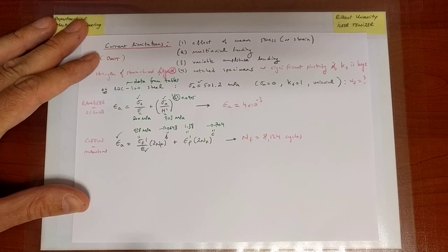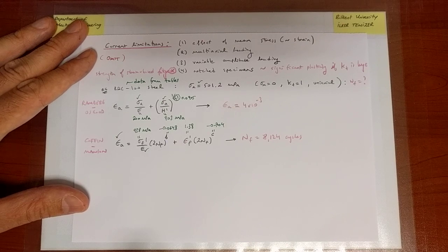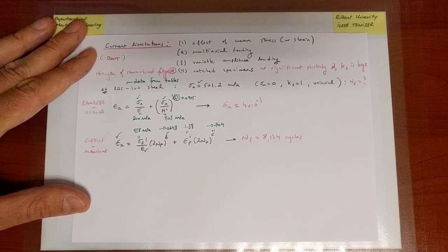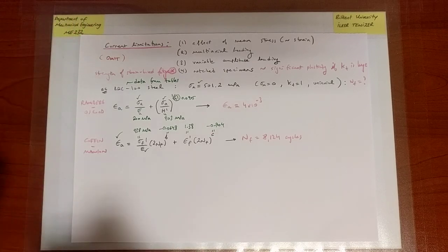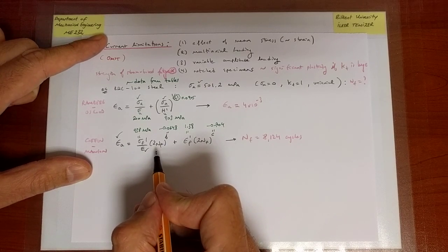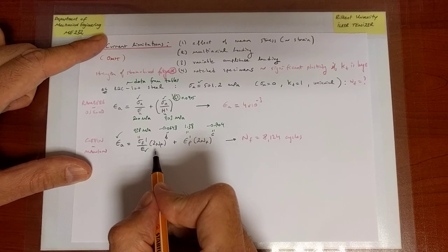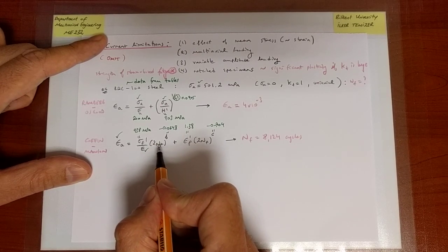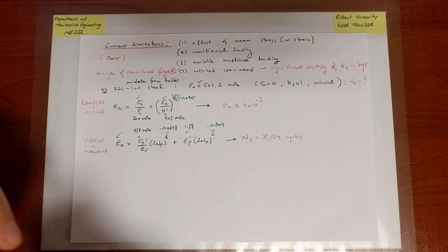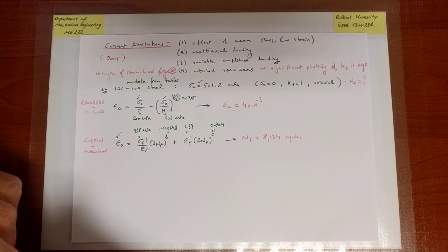So this is not a very small number. It is also not very large. So we are curious as to whether this is more towards high or more towards low cycle fatigue. And this is where the transition fatigue life becomes convenient to make use of. First of all, notice that as soon as I know what Nf is, I can actually predict the elastic and plastic contributions to the overall strain, and compare essentially what they are.